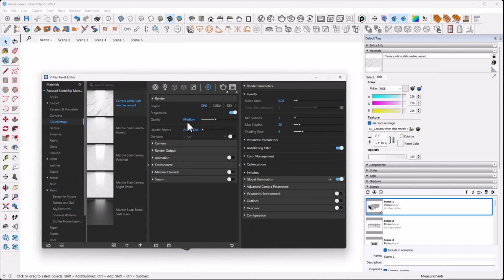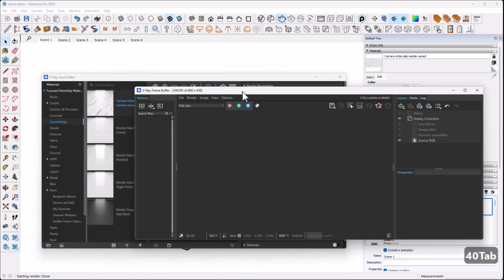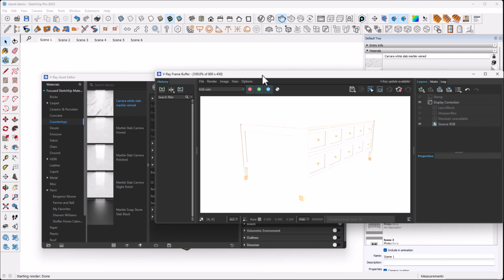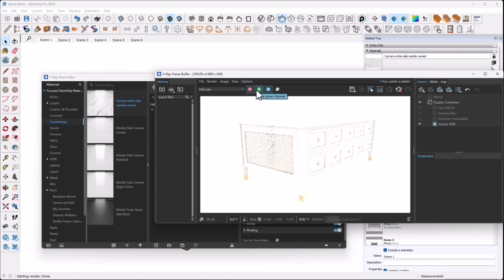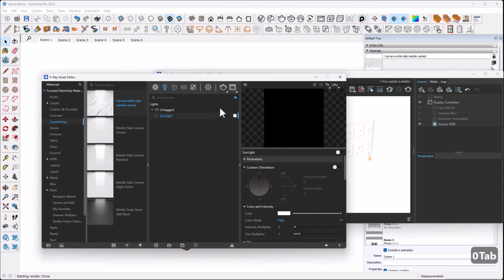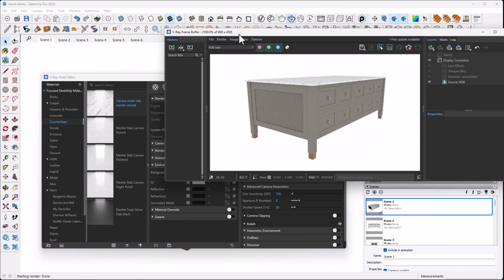And if you want to go ahead and render, just to give an idea of what it'll look like, you can change your settings here, your shutter speed and environment. I'm going to make this a white color. And of course, also turn off the sunlight. So you can see here it's blasted with light, which we don't want. So going to the lighting tab, click off that sunlight, set it to 0. And then go back here and adjust this white value to something that is manageable.